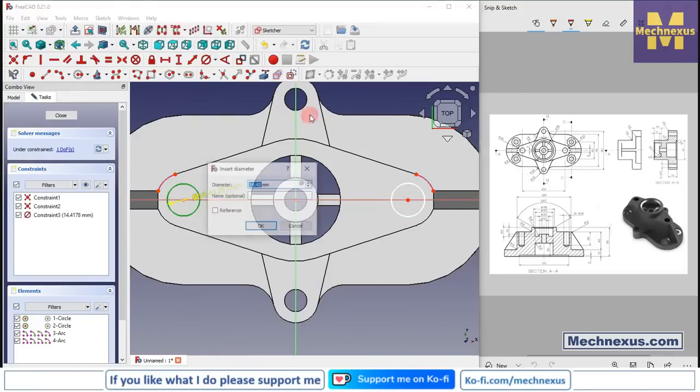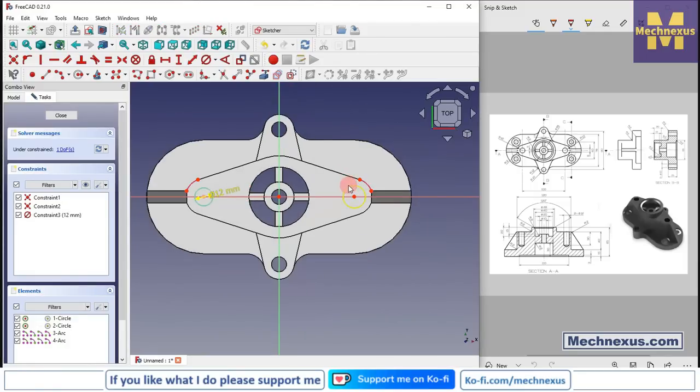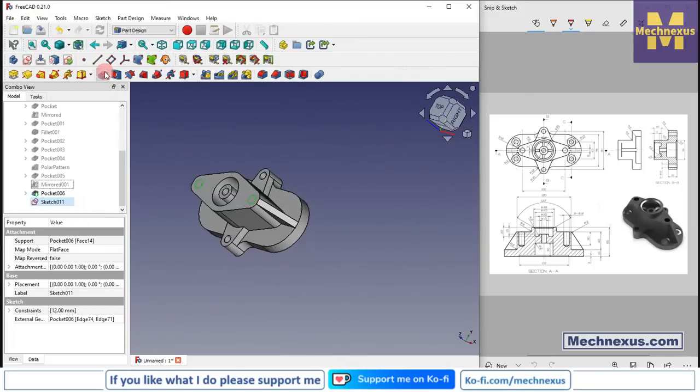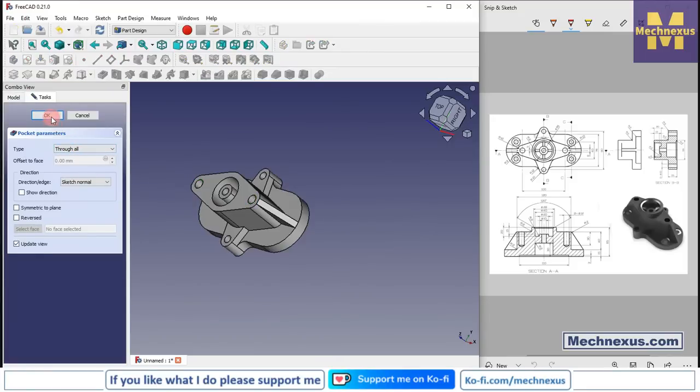Select diameter, provide it 12 mm, and select this and make it equal. Click on close, select the sketch, click on extrude cut, and from here say through all, say OK.